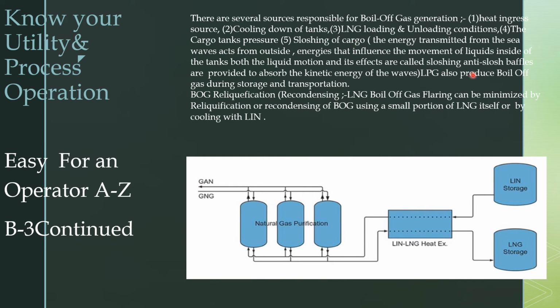is stored. In LPG storage also, boil off gas will be produced during storage and also during transportation. Normally in offshore, you have to minimize the flaring of boil off gas. Boil off gas reliquefaction or recondensing: to minimize LNG boil off gas flaring, it is called reliquefaction or recondensing of BOG, using a small portion of LNG itself or by cooling with lean gas.